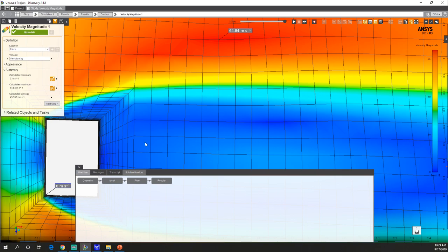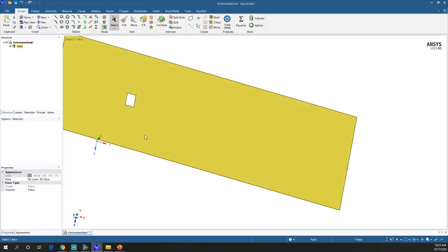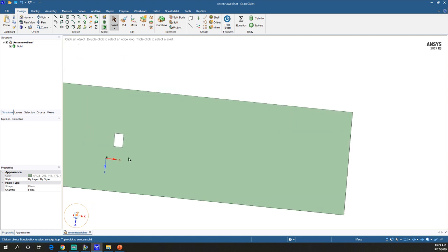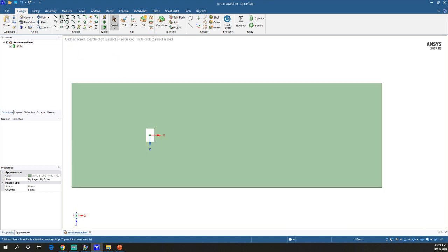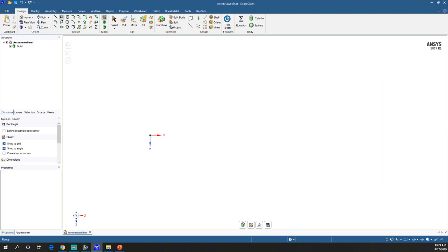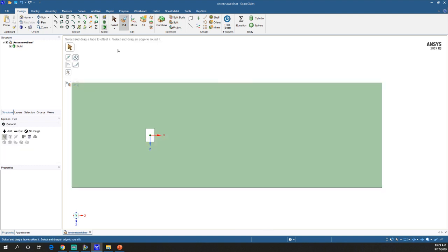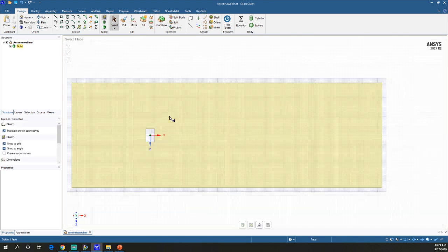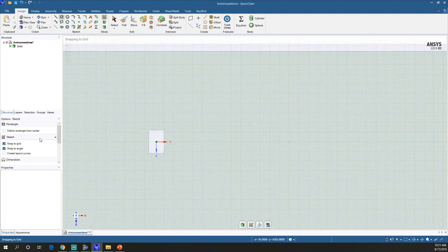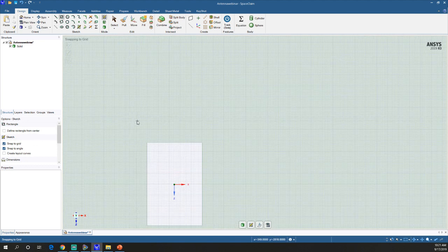So we can adjust this model and set up a region where we want to refine the mesh even more. Usually we want to do a few body lengths downstream. So again, we go back to our CAD model, and we'll sketch on this, and I'll just draw a region. Snap to grid. The grids are very small. Let's do this.